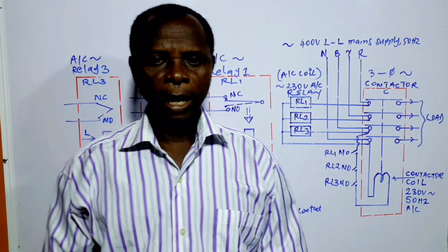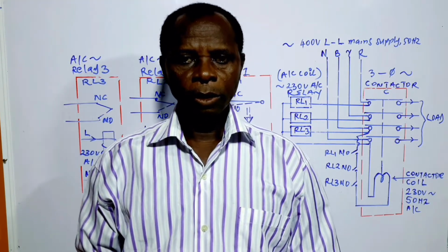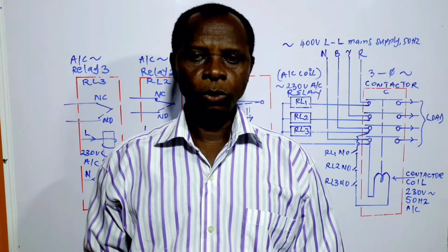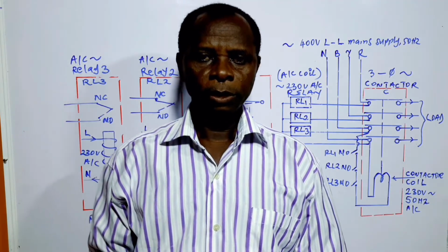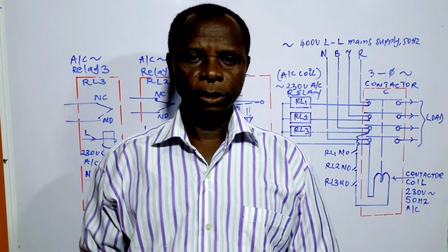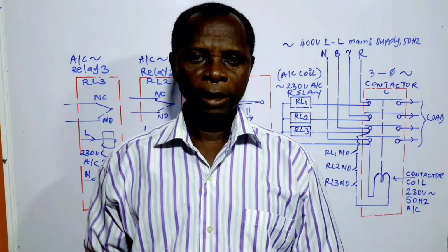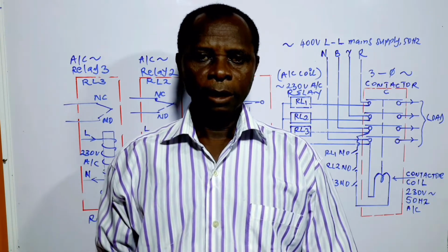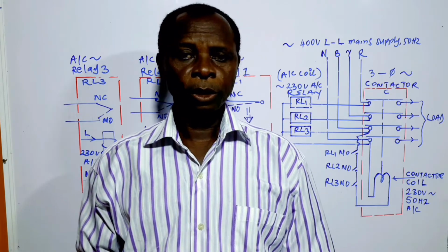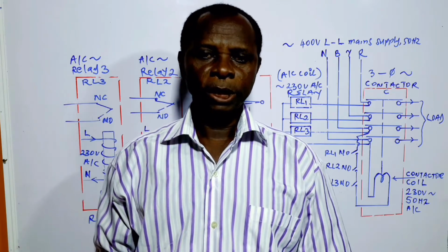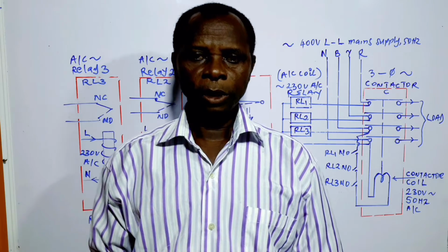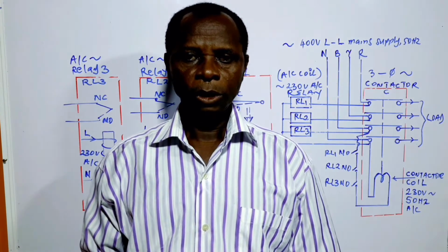The AMF device also creates awareness of loss of one or two phases or even all the phases, and switches off the main supply, such that the generator operator will do the changing over in a situation where the changeover system is manual.